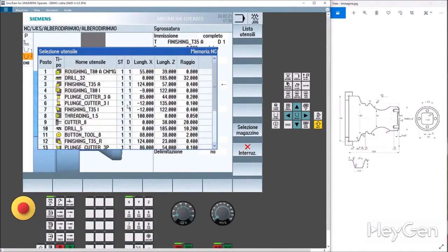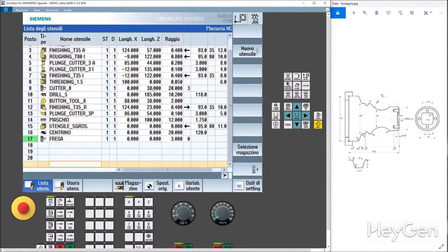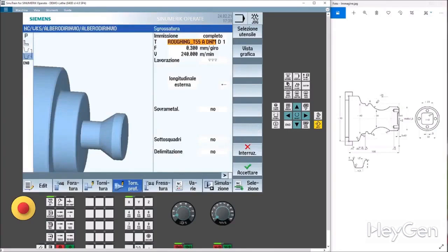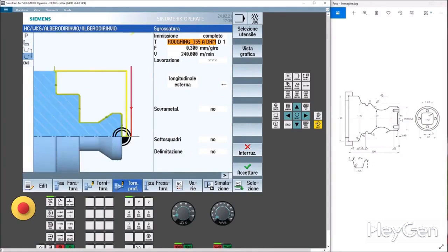Let's proceed to our detailed tool inventory list, where we can review and gather all the essential tools needed for our upcoming tasks. Here, you can see that it has already been modified because I used it in a previous program. So let's go ahead and change the label. The DNMG tool is often used at a height of 15, so 150608 for roughing that isn't too thick. Let's transfer it to the program, telling our machine that it can operate at 13,000 RPM.